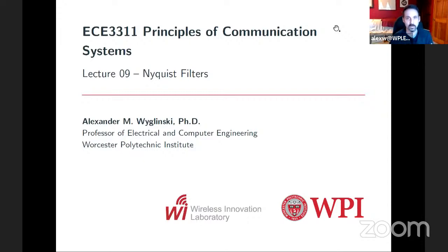So just to recap, what we looked at in lecture 8 is this concept, and it's a pretty serious concept, of intersymbol interference. If we have an environment, the propagation medium, the channel that the transmitter and receiver are connecting through, there is a possibility that if that channel introduces some sort of distortion, it could warp your transmitted waveforms.